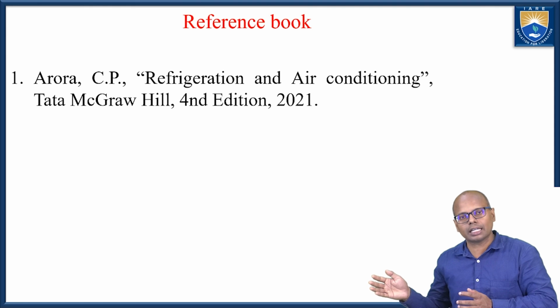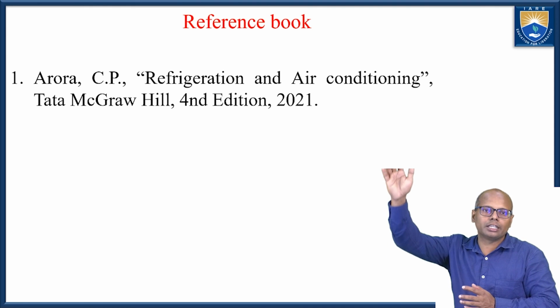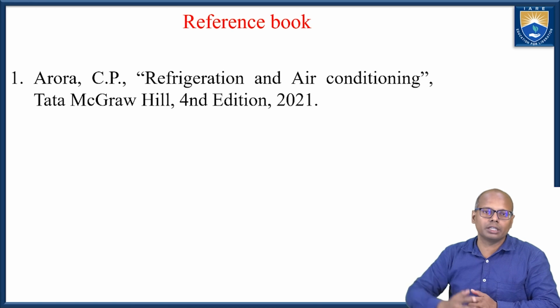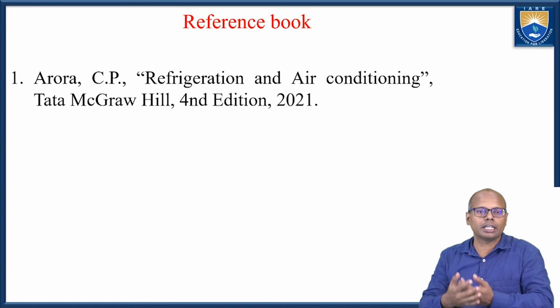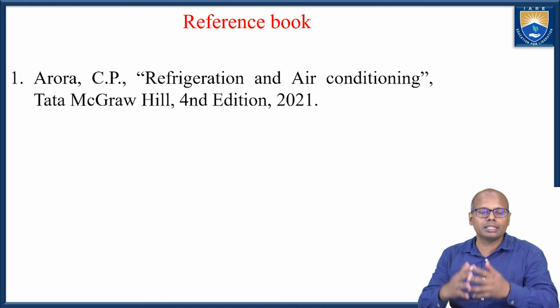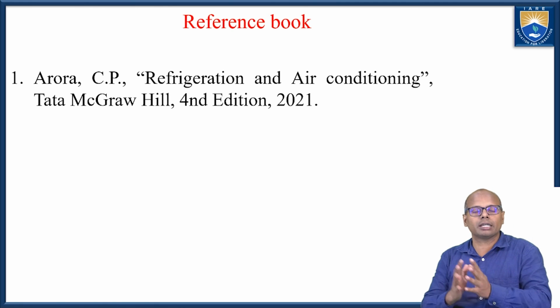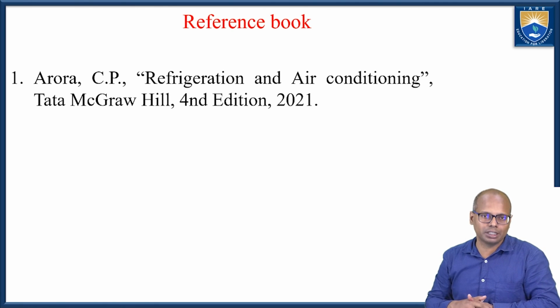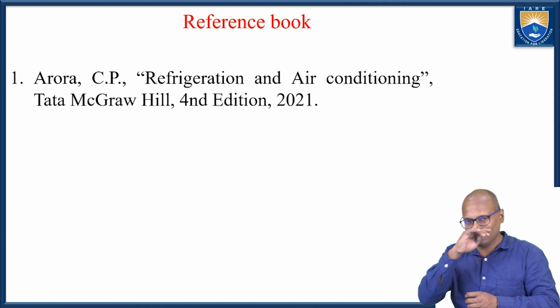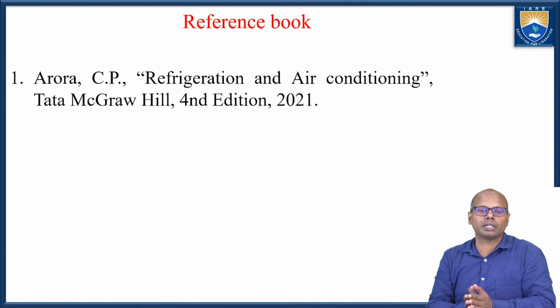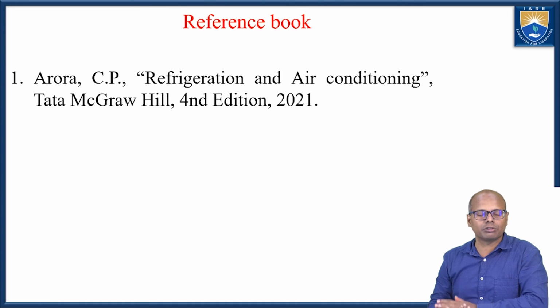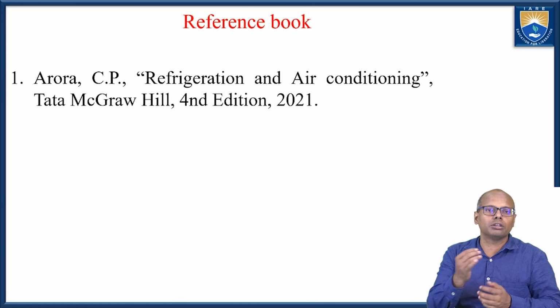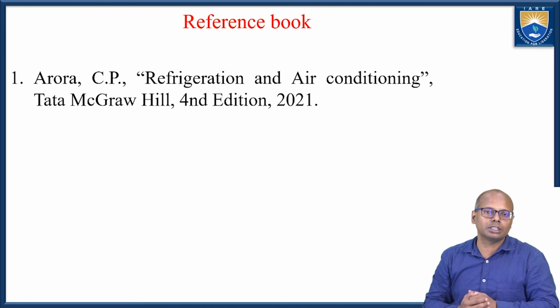When it reaches the saturated vapor point and we compress it, it is going to be superheated. So we get a superheated vapor, and the condenser deviates from a constant temperature process to a constant pressure process. So we maintain the condenser and evaporator at constant pressures in the actual VCR cycle, while in the Carnot cycle we maintain them at constant temperature. That is another deviation.